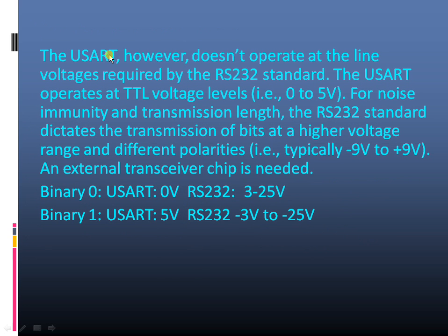Now this USART will operate with TTL voltages, which means logic 0 is represented with 0 volts and logic 1 is represented with 5 volts, or a maximum of VCC. But if you want to use this for long distance communication, then we cannot directly use these TTL voltages. Why?